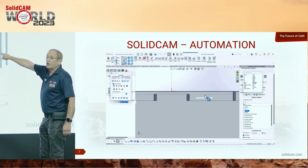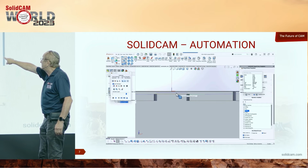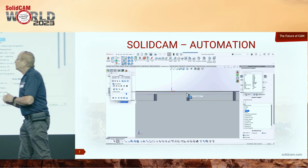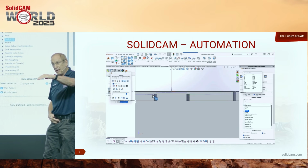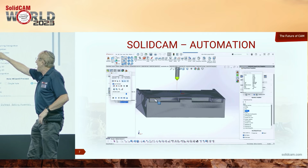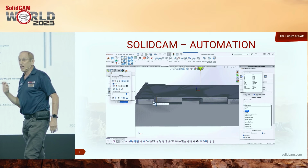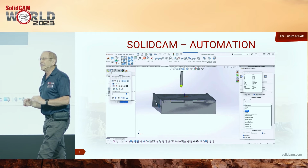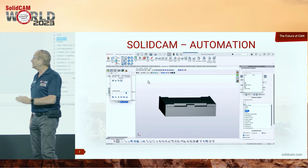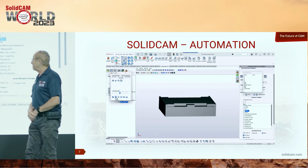Now, look at the boss. That's pretty cool. We're getting towards the boss, and all of a sudden you see the boss is there. It goes up to its minimum diameter, jumps over that particular boss, keeping a chamfer, though, on that edge, and then continuing over to the other side. This is something that I think is a major improvement inside our edge deburring operation over here in 2.5D.